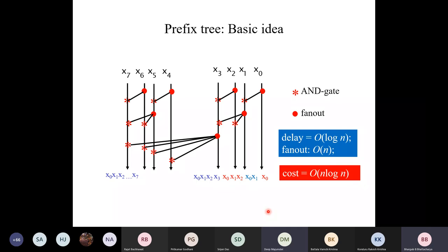And so is fan out a bigger problem or fan in? Because we cannot have an n input AND gate for arbitrarily large n, but fan out may not be that bad also. Yes, fan out is also a problem, because fan out means the output of the gate has to feed so many inputs. The power problem: they have to supply the current needed, so the power increases. Both fan in and fan out are problems; both create different types of problem.